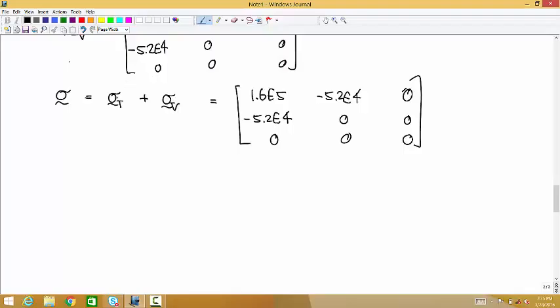So what that question is asking is, somewhere there's a coordinate system where the shear stress is as big as possible for this same point that we're representing here. What's the shear stress for that coordinate system? It could be this one, but most likely it's not. Okay, so what do you have to do that? 2 steps. Eigenvalues? Yep, first you have to find the eigenvalues, and then you can just use that formula to find the maximum shear stress.